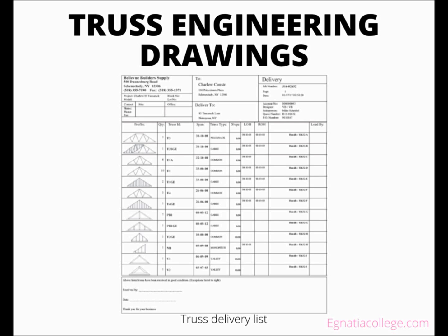Large trusses can be too large to transport to the construction site, so they are delivered in two parts. The top of the main truss is flat, so the piggyback truss can be applied to it after it is in place. Slope or pitch, the example here shows slope or the unit rise of the roof.